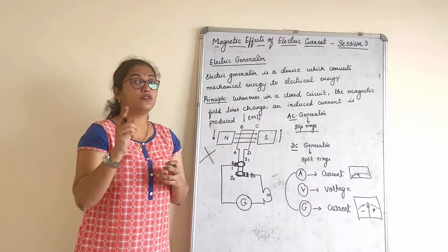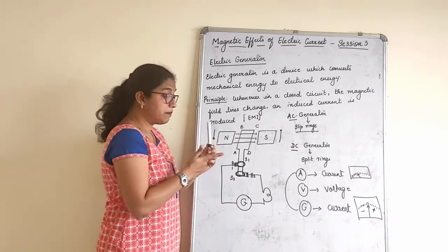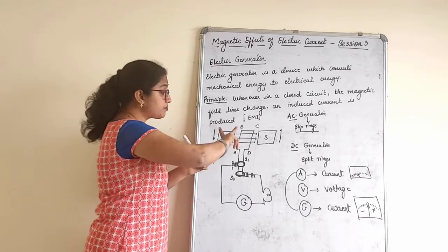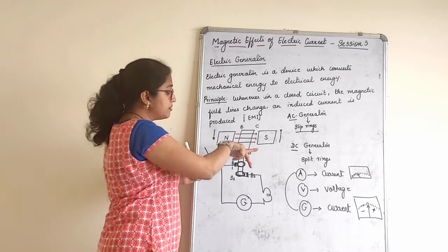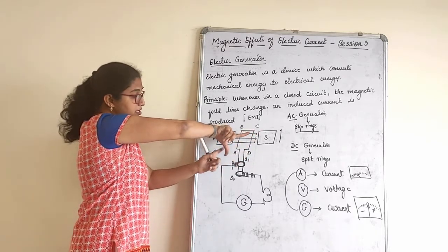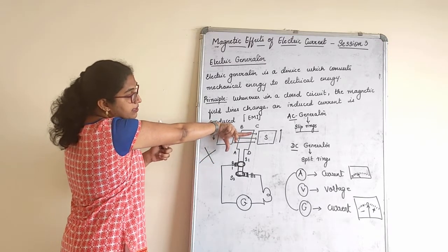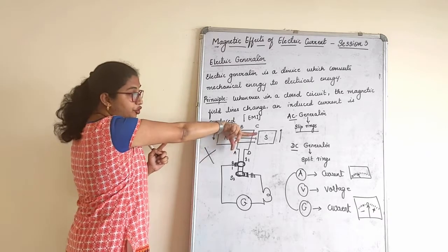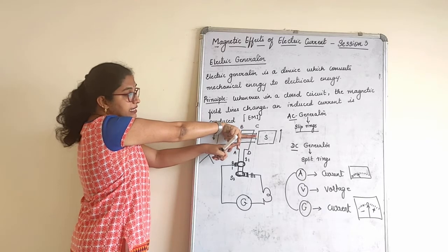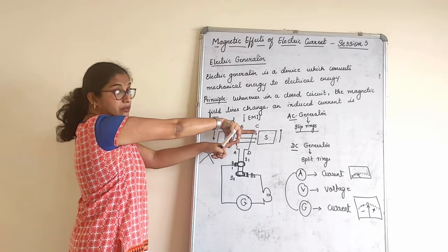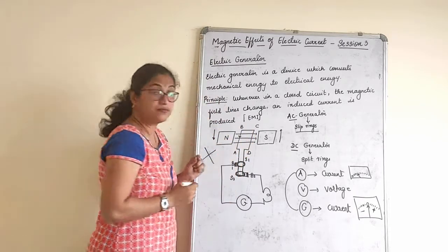I know the direction of the motion of the conductor now. I also know the magnetic field. Let me apply the right hand rule. If I apply the right hand rule, it actually comes like this. So, this is the motion of the conductor, downwards. Now, this is my magnetic field, the forefinger. Where is the center finger pointing, if you can see? The center finger is pointing down, right? So the direction of current here is down.